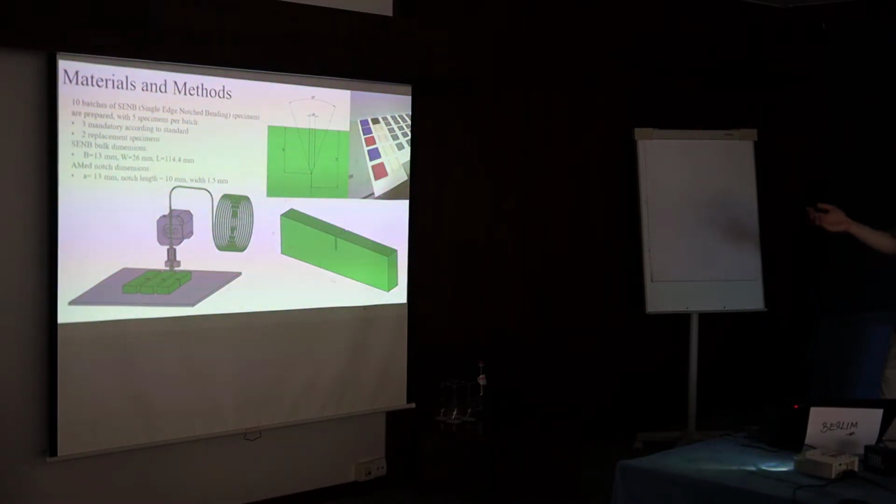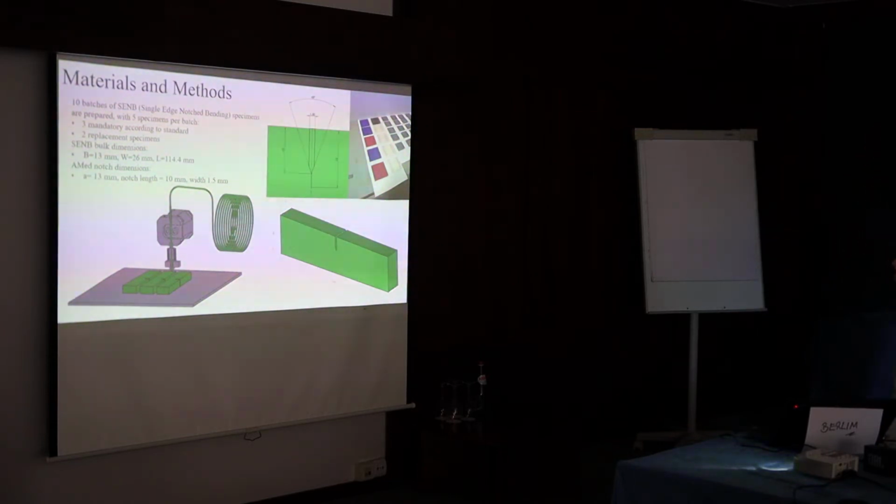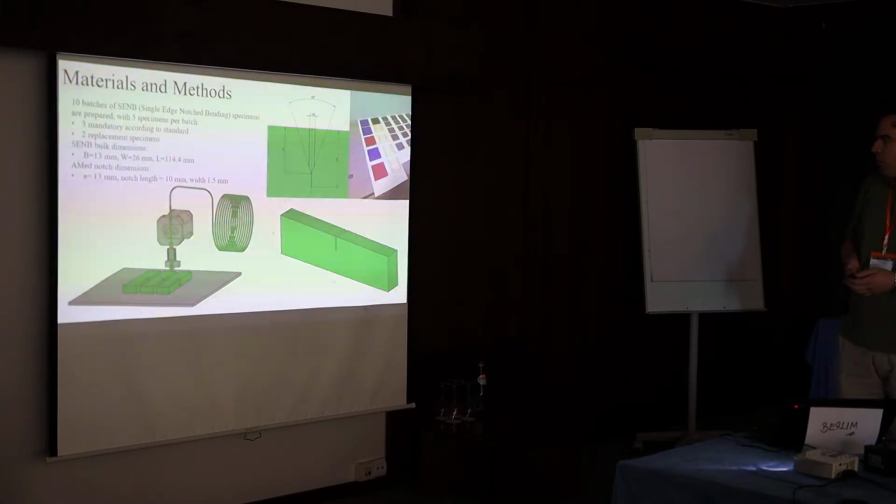In bulk, these specimens were 13 by 26 by 114 millimeters, and the models were created according to the standard. They were printed with the biggest surface placed on the platform. Here are some finished specimens of PLA and PLAX material.